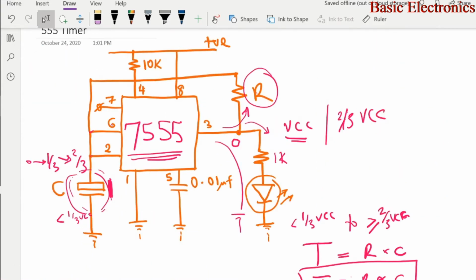Here is a basic diagram of the Astable Multivibrator using 555 timer, or you can call it an LED blinker. Here we tied pins 2 and 6 together as we mentioned earlier on, because this is the only way we can control the internal logic of the two comparators. When you power the circuit on, momentarily this capacitor C is going to be a short. Remember, we talked about this in the tutorial on basic components. Please look at capacitors again.